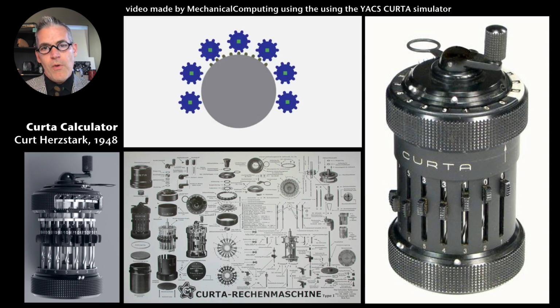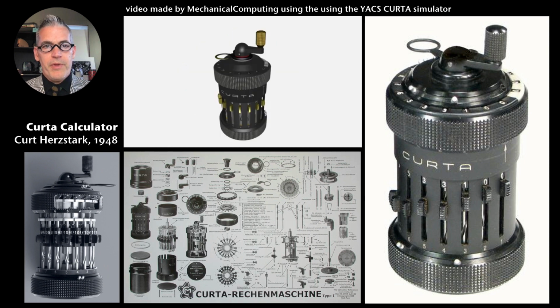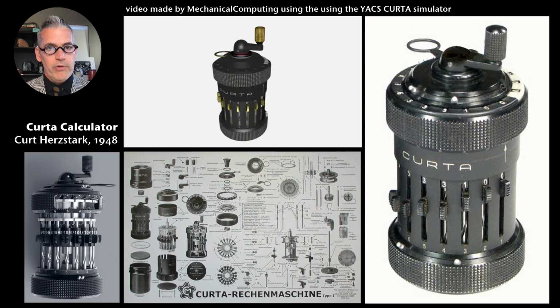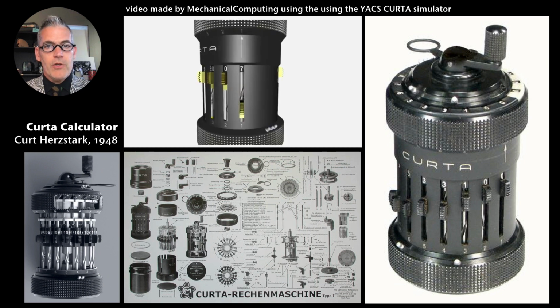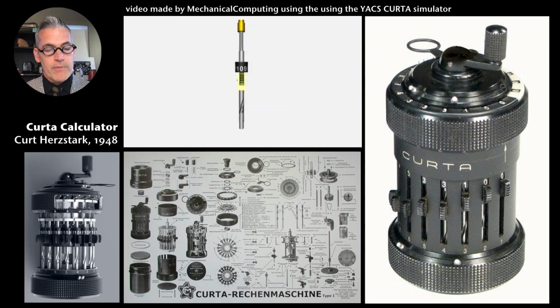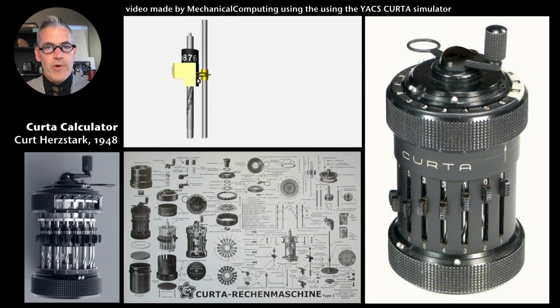One of the things you should know about the Curta Calculator is that it works with haptic feedback. The knurled surfaces around the edge tell you where to hold it and where to turn the crank. Turning the crank clockwise adds, and counterclockwise subtracts. But then you can lift the top ring and turn it so that you can perform addition or subtraction in orders, by tens or by hundreds instead of one at a time. So you can do much larger sums.